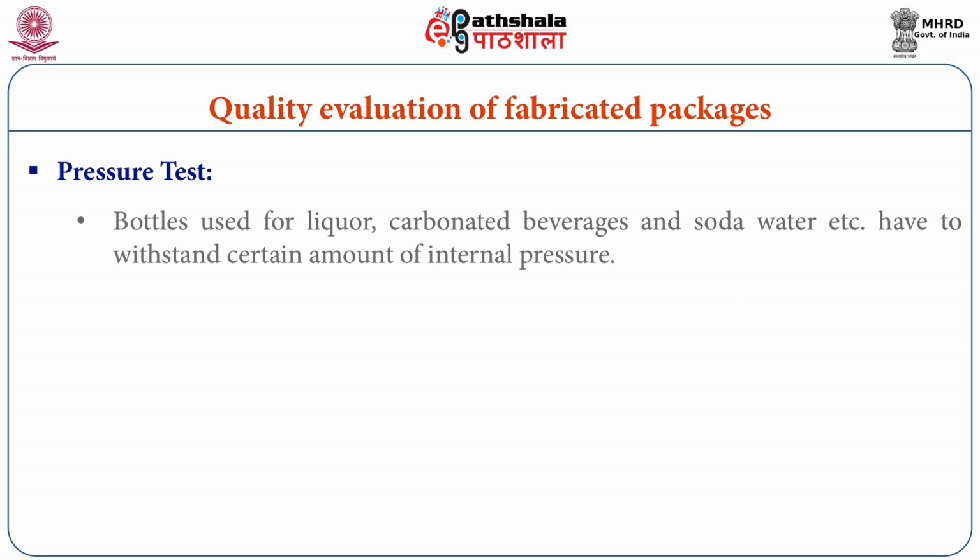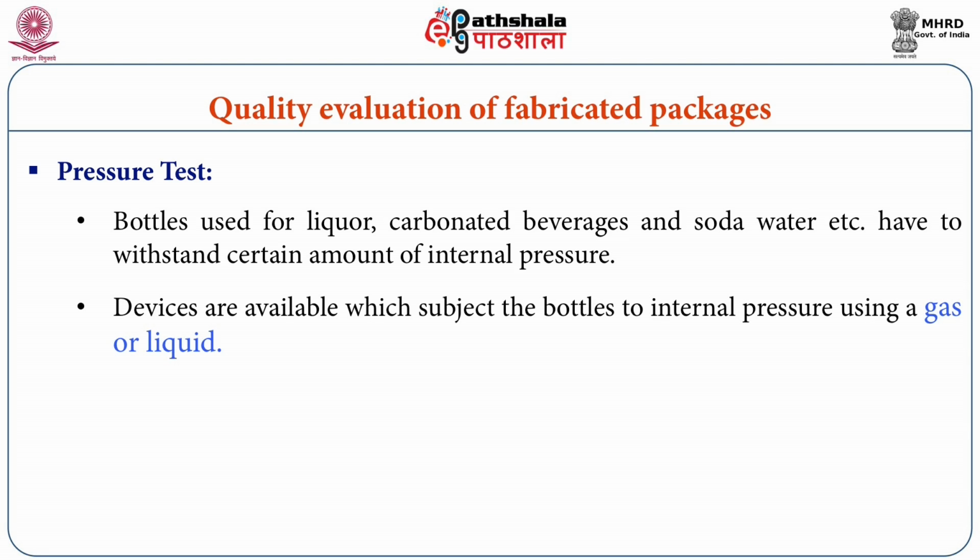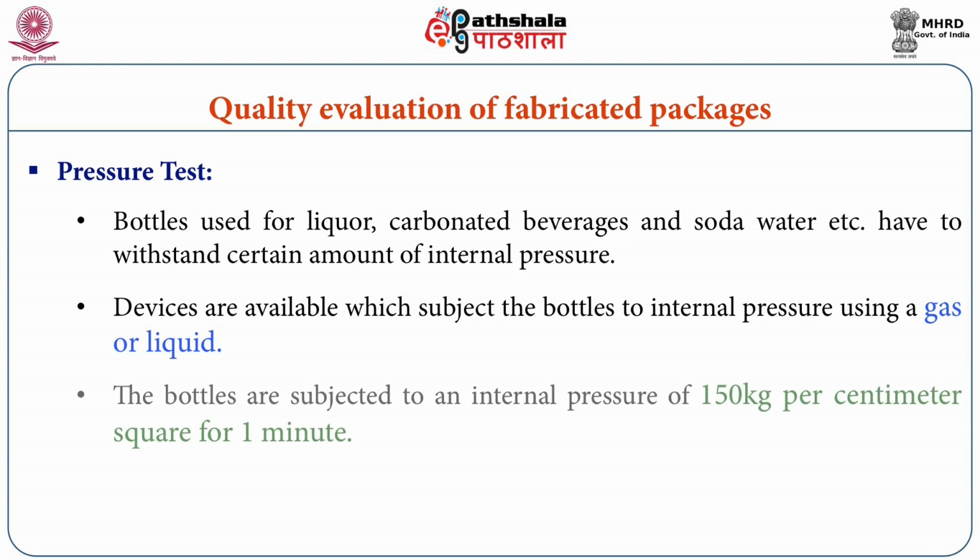Pressure test. The bottles used for liquor, carbonated beverages and soda water etc. have to withstand certain amount of internal pressure. Devices are available which subject the bottle to an internal pressure using a gas or liquid. The bottles are subjected to an internal pressure of 150 kg per centimeter square for 1 minute.